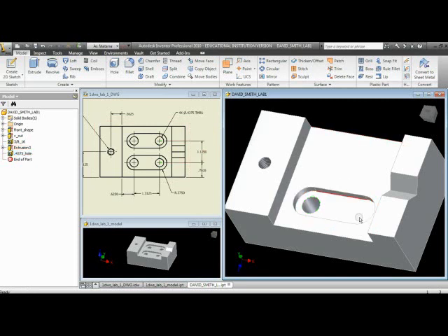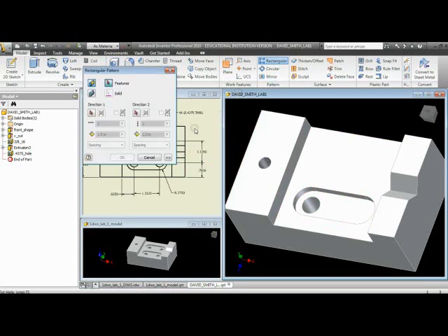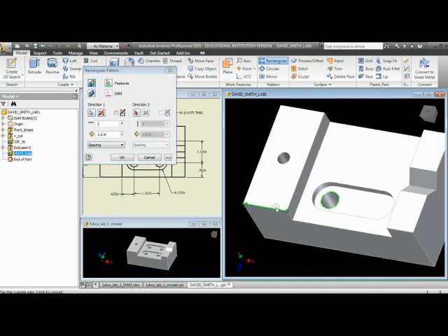That's good. Now, when you're putting in holes, put them in as holes. Do not draw a circle and extrude it down. The information that we need for this drawing, if you put it in as a hole, it remembers it as a hole, not as an extrusion. Therefore, we can put the symbols on there like they need to be with one simple move on the 2D portion of this package. Hole number 2, we might choose to name that 0.4375 hole.